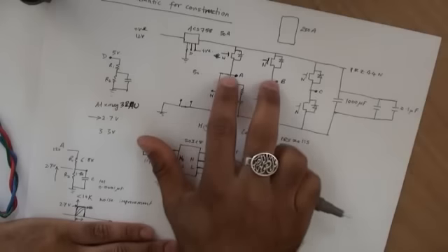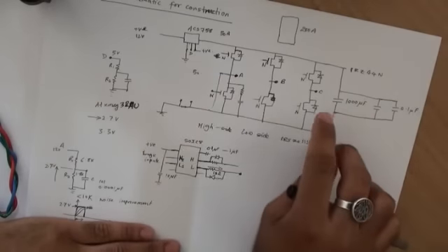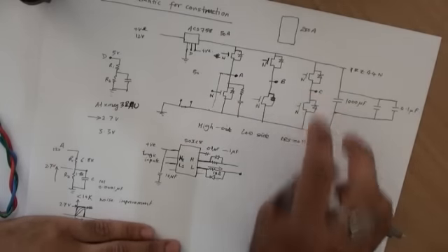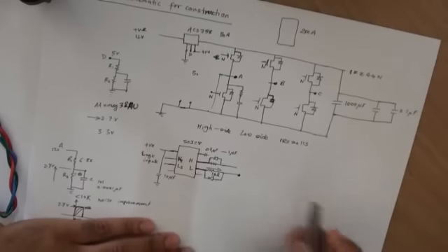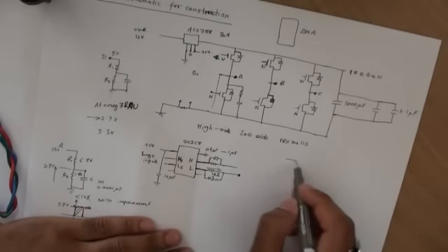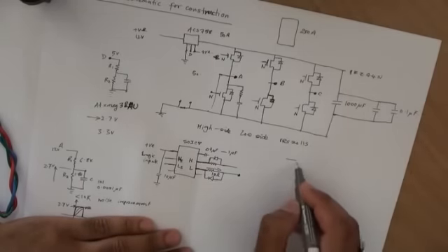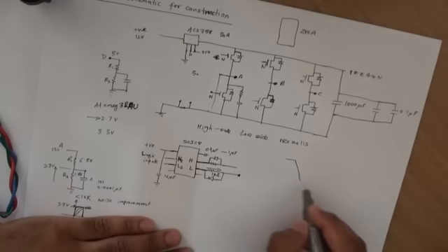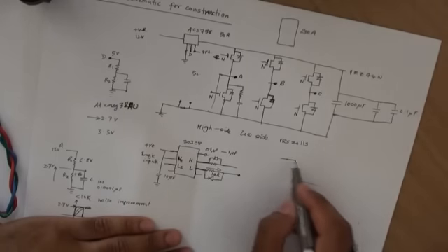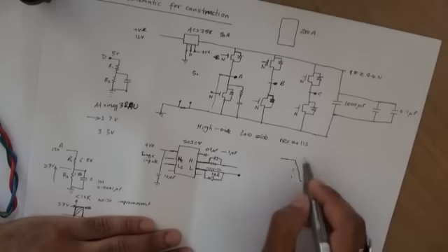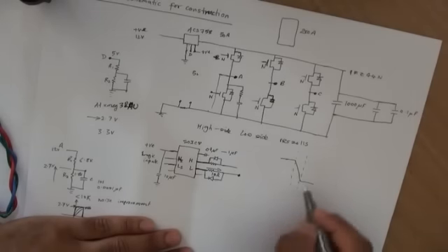So as you're firing 2 of the phases, you're looking at the back EMF on the 3rd one, and the characteristic for the back EMF is that, depending on the rotation and the commutation steps, it goes from maximum to a minimum, and this is what you are looking at.